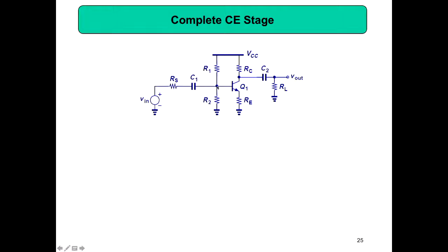That is a bias. Then that 0.7 volt will not come to this side because of this capacitor. The capacitor will block that DC signal, and from here only the AC signal will go this way. So your AC signal will pass through the capacitor and come here, and then that AC signal will be riding on that 0.7 volt. The 0.7 volt you can measure here using an oscilloscope. You put your probe here and then ground, then you will see 0.7. But when you measure here, you don't see that 0.7 because this capacitor will block that DC. It will not come to this point. So that is a coupling capacitor.